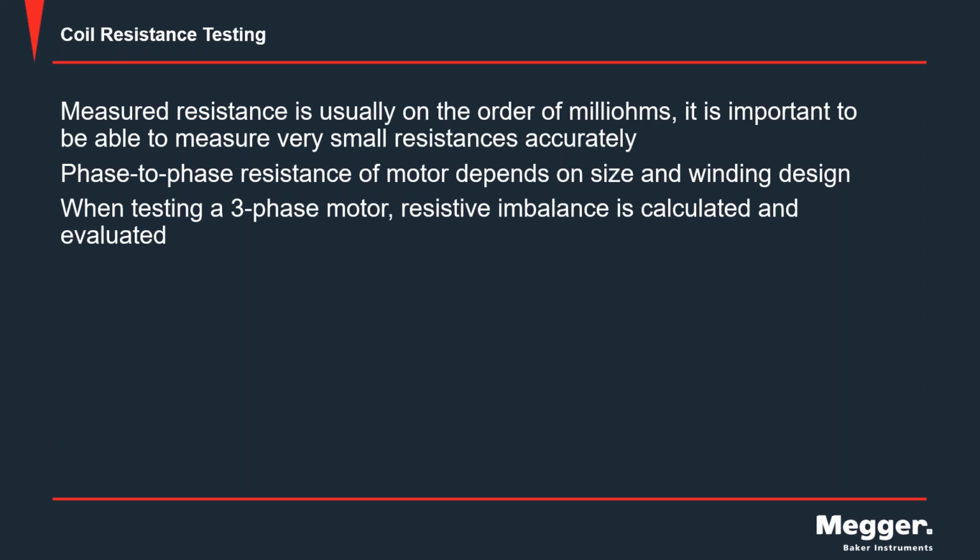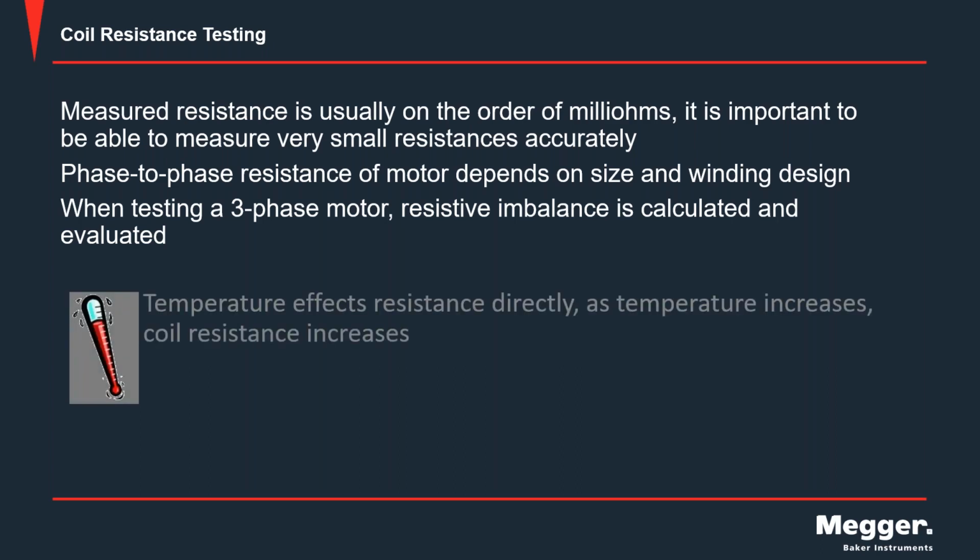When we test three-phase motors, we're going to look at a resistive imbalance. So we take the three measurements phase-to-phase, perform an imbalance calculation on them, and then evaluate that number. Temperature also affects resistance directly. As temperature increases, coil resistance increases.